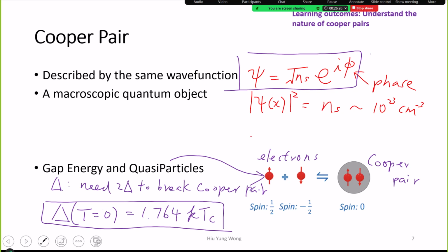And how do you detect the photon? So they use this superconducting nanowire. That is one approach, instead of using the so-called Geiger counter, right? The Geiger counter is a PIN diode reverse biased so that when your photon goes in, you generate an electron-hole pair, and then you get an avalanche and you know that there's a photon that just came in.